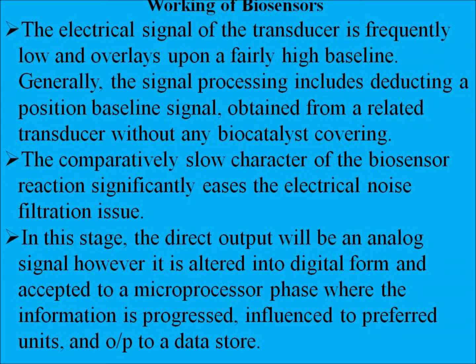The electrical signal of the transducer is frequently low and overlays upon a fairly high baseline. Generally, signal processing includes detecting a baseline signal obtained from a similar transducer without any biocatalyst covering. The comparatively slow character of the biosensor reaction significantly eases the electrical noise filtration issue. In this stage, the direct output will be an analog signal. However, it is altered into digital form and passed to a microprocessor stage where the information is processed, converted to the preferred unit and output to a data store.